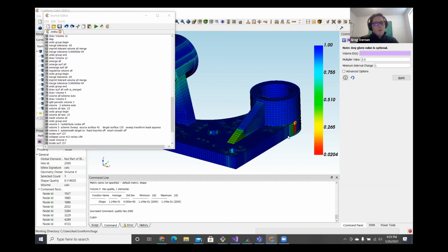So my recommendation is, first of all, to try not to work with mesh-based geometries in the first place if you can. Sometimes your customers might have a CAD model in Creo or SolidWorks, and they're giving you an STL file of it, and that STL file can only be processed in mesh-based geometry. My suggestion in that case would be to request that they give you either the native CAD geometry and then use one of our CAD translators, or to export out a STEP file or an ACIS .sat file so that you can actually operate on the actual CAD. Sometimes, however, that's not possible.